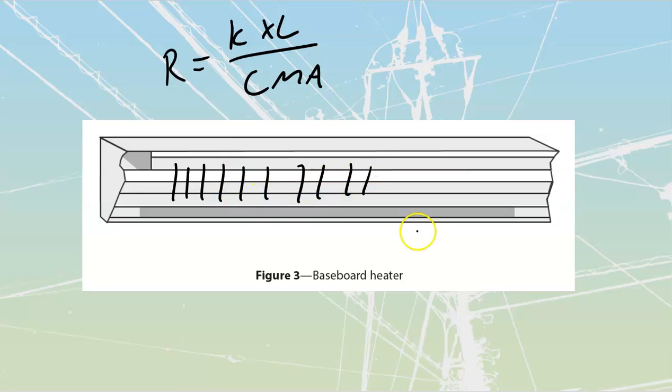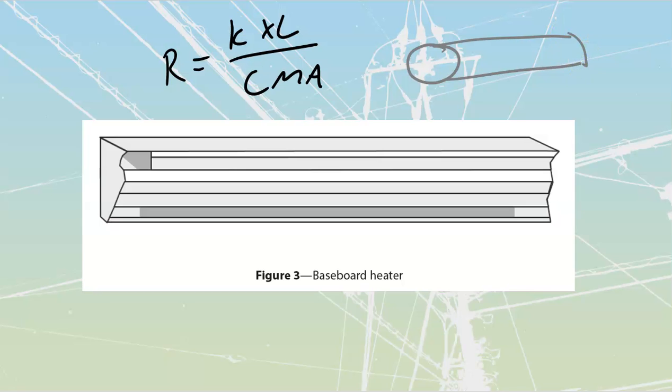The reason we've got all those fine aluminum fins is because aluminum carries heat very well, and heat always moves from areas that are hot to areas that are cool. It's the basic laws of thermodynamics. What we have inside of those fins is a ceramic tube, so I'll just draw this out over here. We're going to have a long ceramic tube, and in the very center of that ceramic tube there is going to be a nichrome wire. Sometimes it's coiled, sometimes it's not, but that nichrome wire just goes through the inside of the ceramic tube. The ceramic tube is designed to be the insulator and the support for it, so you can touch those fins. Those fins are literally just sitting around the ceramic tube.